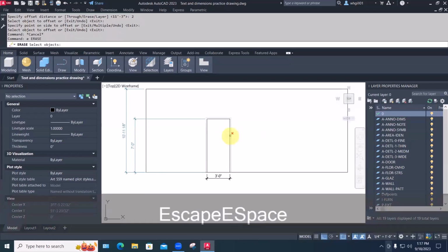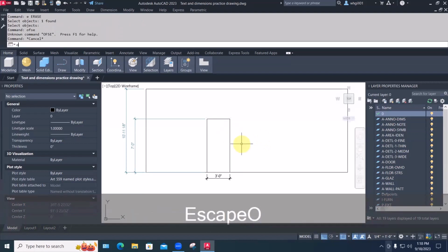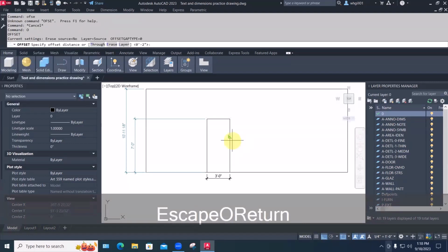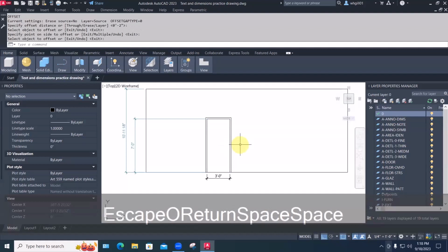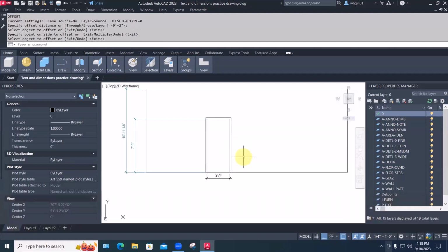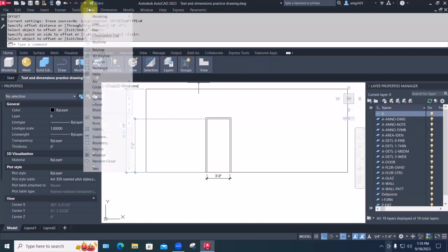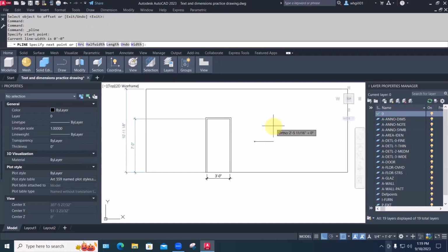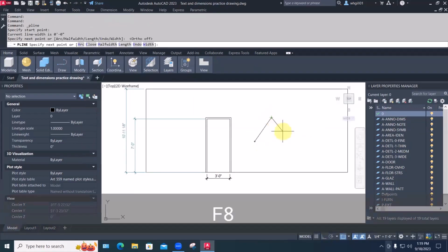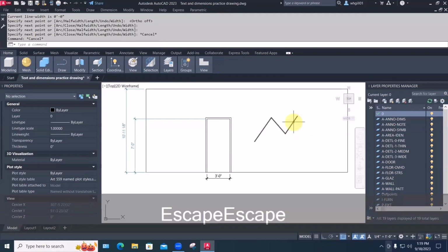You'll notice that when I offset this, O for offset, I could do that as one element, because what I had drawn there, this guy right here, is a polyline, which is any combination of lines and arcs that touch at their endpoints. So draw polyline. You can see it's a line and a possible arc. Start out by drawing lines. I'll turn ortho off, and I can draw that, and it's all one object.